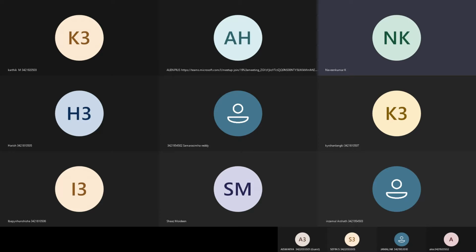Based upon the application and the load intensity, you decide the appropriate shape of the steel section, as well as the type of connection. Once you go for steel section construction, the connection is the most important part. Why is the connection important? The two sections have to be connected, and it can be welded also. Either you can go for welded or you can go for a bolted connection. So you decide this also.